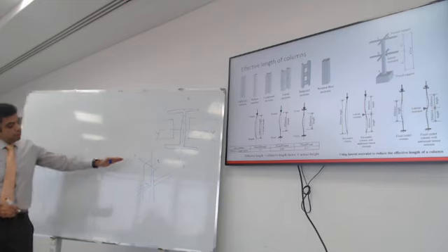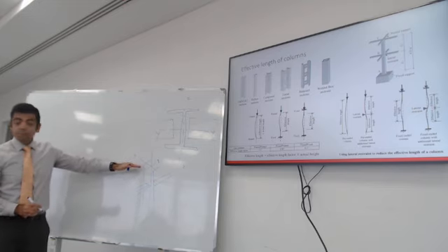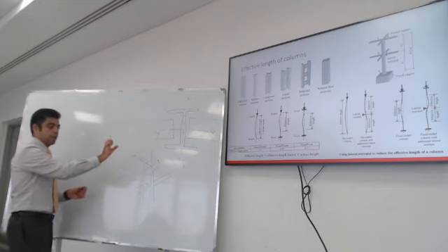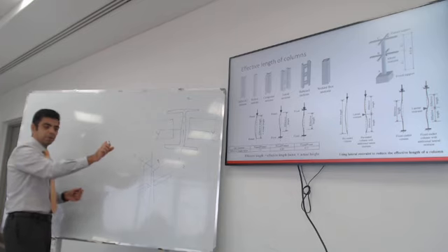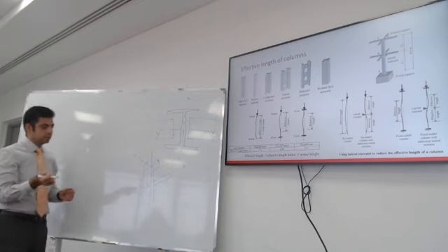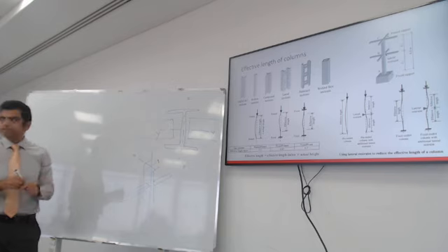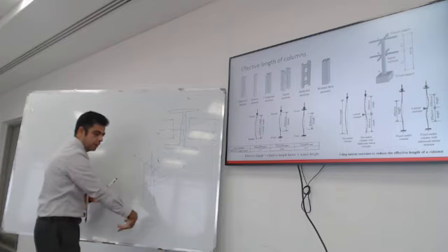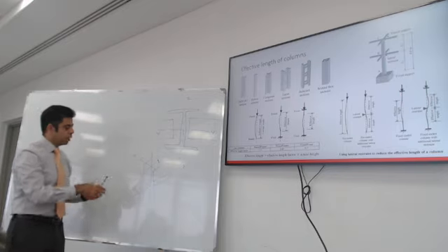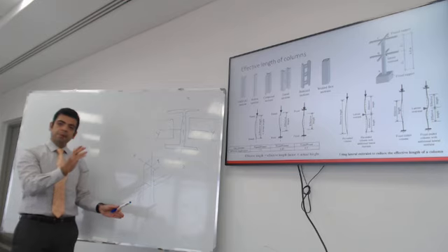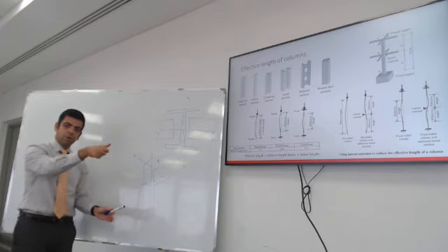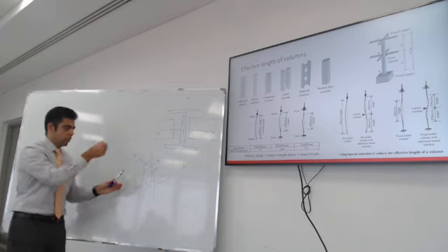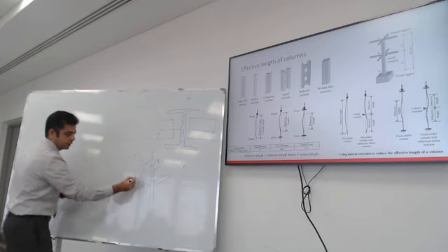Is this beam braced when it buckles about Z, or is it braced when it buckles about Y? It will buckle on Z, from the direction of Z. It could buckle about both. Yes, it could buckle about Z or about Y. But this beam is bracing the buckling about Z or about Y? About Y, it will deflect like this.